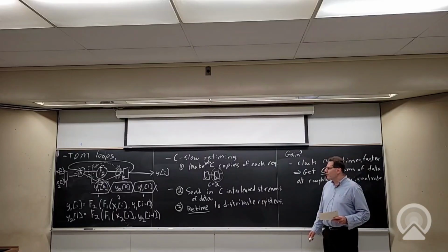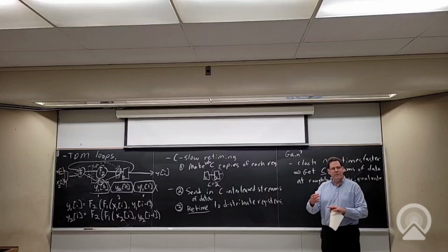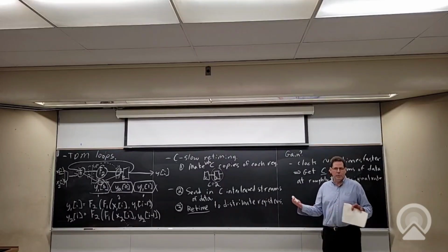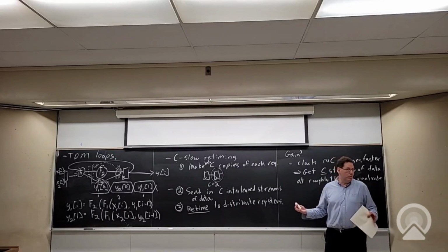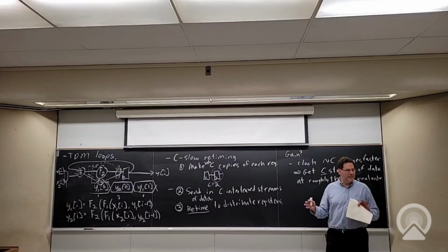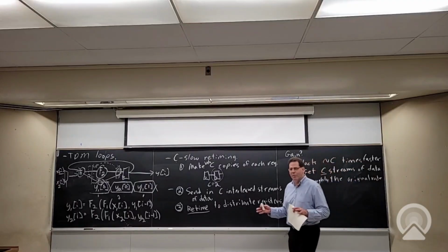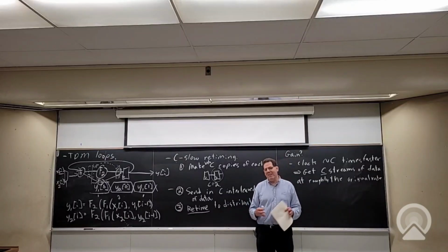The reason it doesn't do it for you is it is actually interleaving data streams, so it does require some higher level knowledge of is that okay and how do I do that? CAD tools don't like to do anything where they're like, I just changed your design to something else that sort of might match what you want. They want to do exactly matches the input HDL, because anything else is kind of chaos, right?